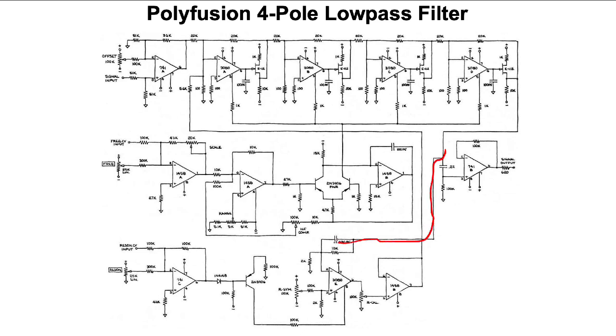What's important is that it goes into the inverting input of the OTA here. And again, we're just using this resistor to convert that output back into a voltage. The resistor is not part of the feedback loop of an op amp, so we are not getting any inversion from that. It just gets simply buffered, and then it's coming back to the input here.